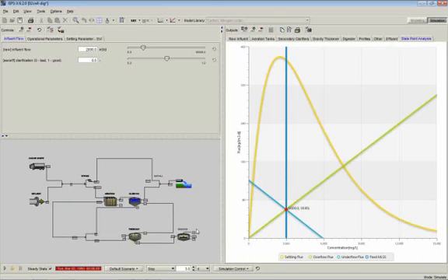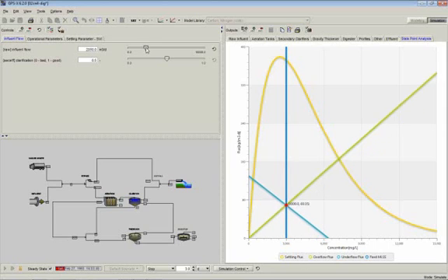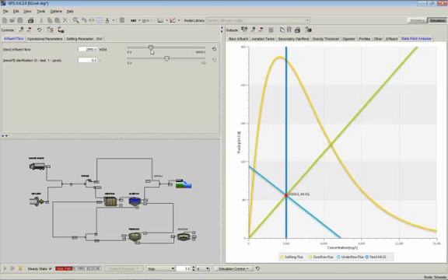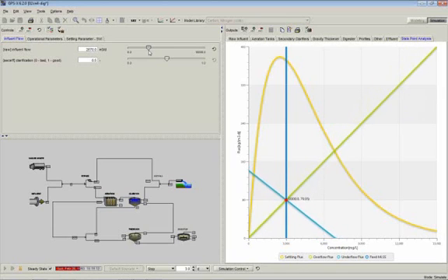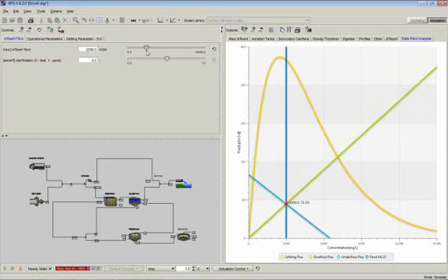This is a new graph, and we can output this directly to an Excel spreadsheet. And now it's plotting this state point analysis as well. You specify what concentration you want to draw your boundary at there, and then all of the other information is picked up directly from the variables in the model. So if I'm running a simulation here and I'm changing the amount of flow that's going through that particular system, as I'll do here in one moment, once that's running, you can see here that the model picks up those numbers right away, and it responds to the different fluxes as we have different amounts of flow going through that clarifier. So that's updated continually all the time.